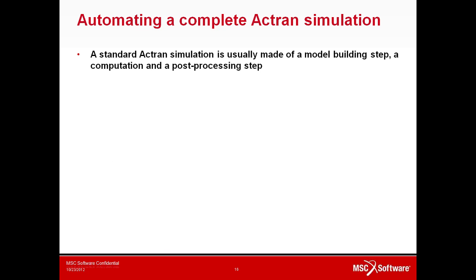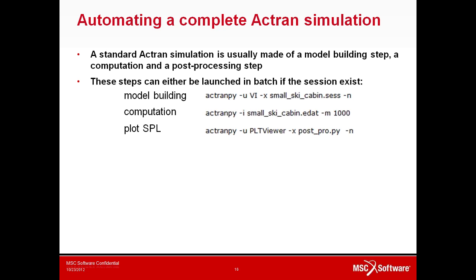If the pre- and post-processing steps of a typical analysis are already optimized, one last optimization usually consists in running the complete simulation in one step. This can usually be performed in two ways. As all sessions can be launched in batch mode without the graphical support, the user just runs the different commands either manually or in batch. This can be performed without graphical support directly on a cluster environment, for instance.